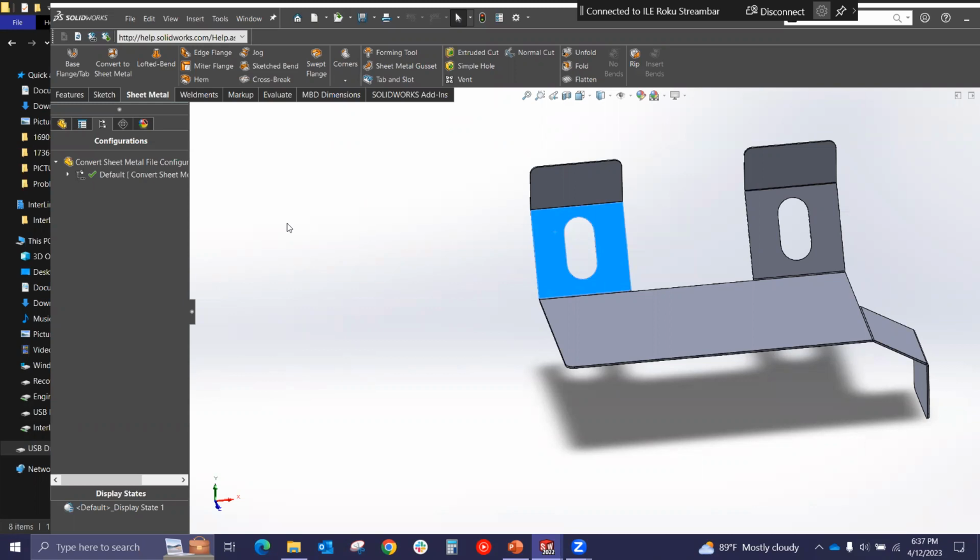Do you prefer to see DXFs with bend lines? I've heard in some places that they don't like to have them because it messes with the laser speed, the laser cut. With the nesting software that we're using, which is Bysoft, it was all in one. So you can select what to cut, and you can select what the bend lines were. The software already knew that for this portion, these are the lines being used for laser cutting. For the bend portion, these are the lines being used for bending.